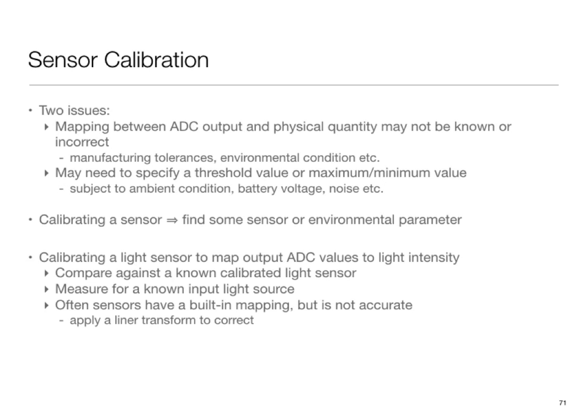And very loosely speaking, you can employ one of a few approaches. One is you have a depth sensor deployed in the field, you bring a costlier, high quality sensor, and then you compare the reading. So that's calibration against a reference sensor. Or you can calibrate by feeding it a known input. Oftentimes sensor chips that you buy have a self-testing capability. All that it refers to is that they have circuitry to feed a known signal at the input to the sensor so that you can compare the value and then work with it. So there's a variety of approaches, and many sensors provide built-in self-calibration.